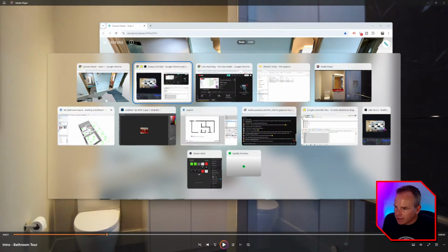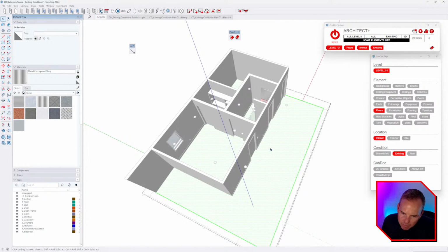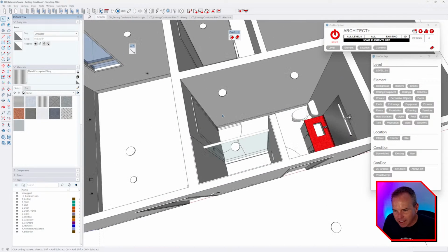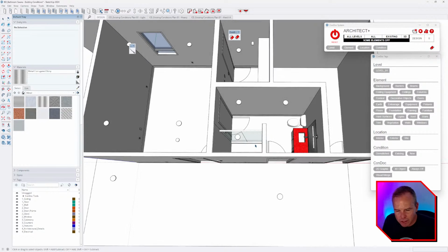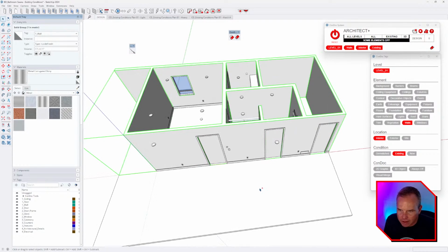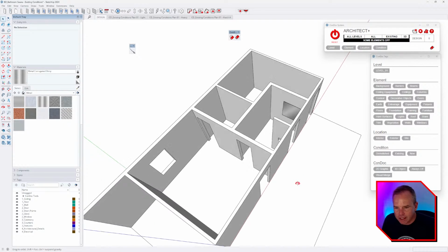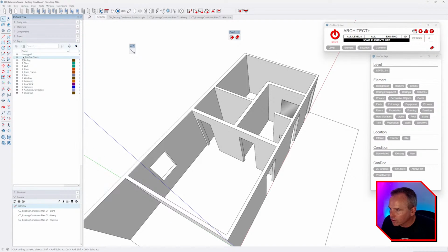So back to SketchUp, we need to kind of break up the textures on the floor, but really the only thing we need is the bathroom, which is the only thing that I can tell is different. So to do that, this is a perfect job for the Express tools. If I select my walls and floors and then isolate them, it automatically turns off all those tags that weren't selected.